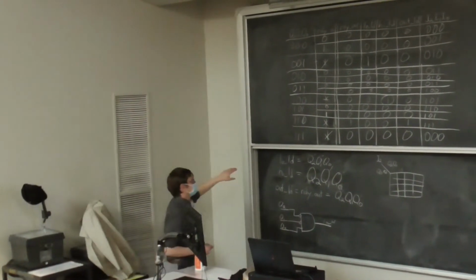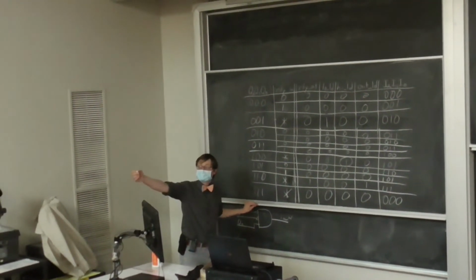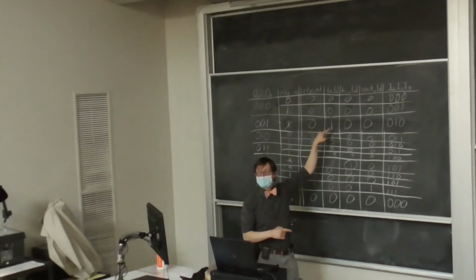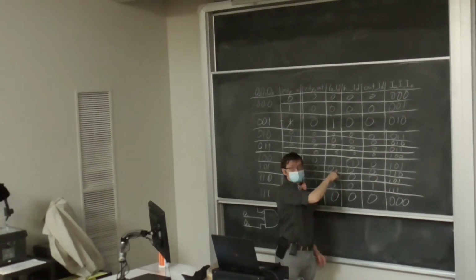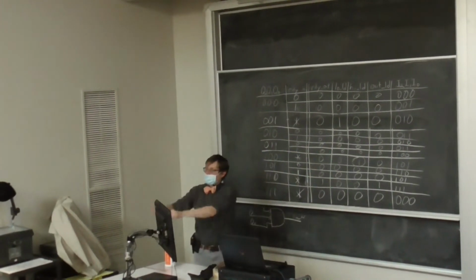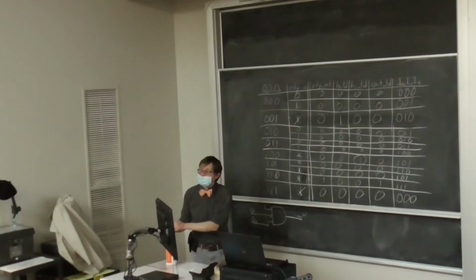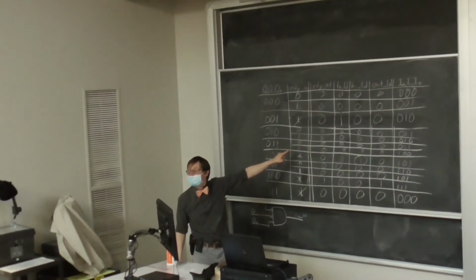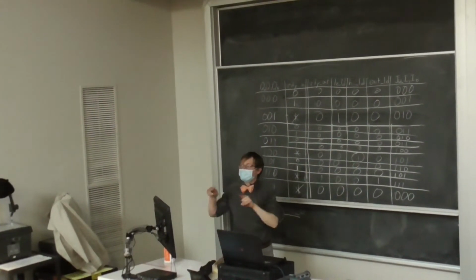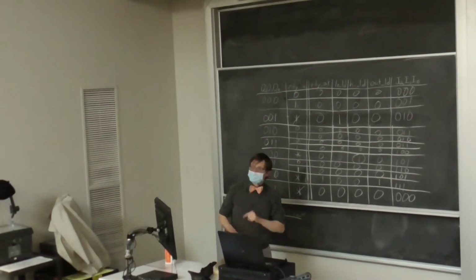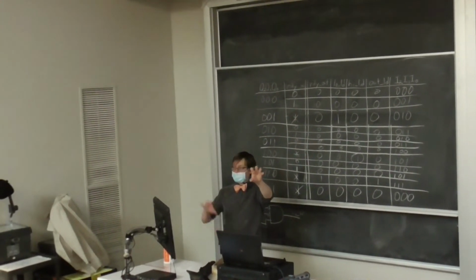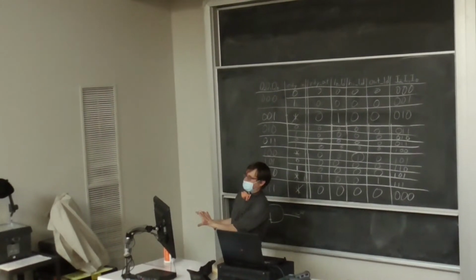So for example, just in terms of a sequence of operations that would be possible if that were the case, right? Let's say that the low load stayed 1 until somewhere in this vicinity, right? The data has changed. The data in line has changed. A new ready in signal has been received. So that means the data has changed. Which means that if this were still 1, you would load that data into both registers, right? Which completely defeats the purpose of what you're trying to accomplish with the IC, right? Because you want to load one, load the other, smack them together, output that, right?